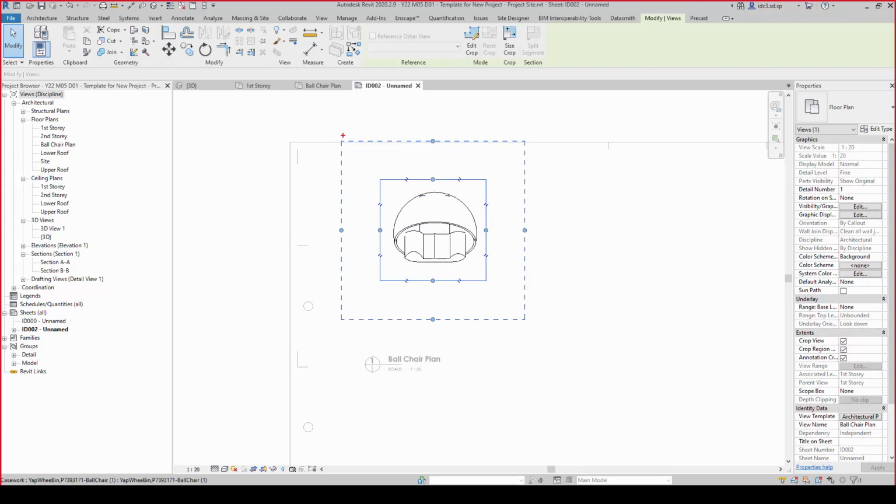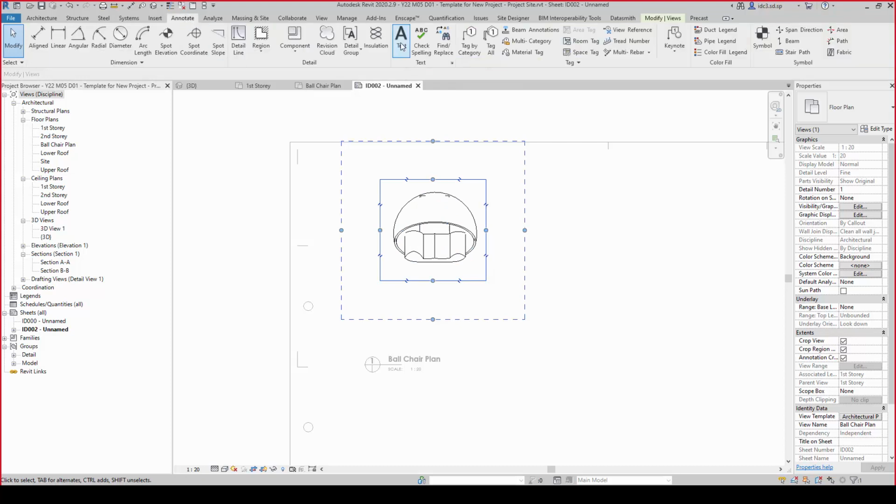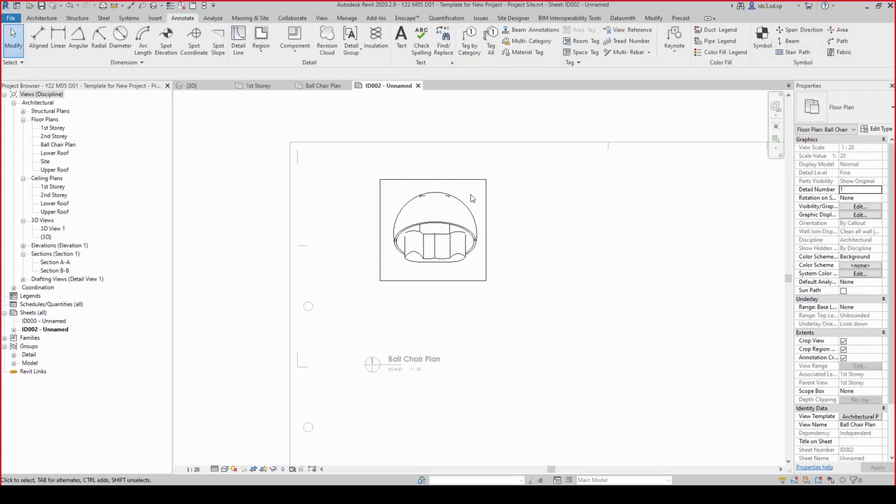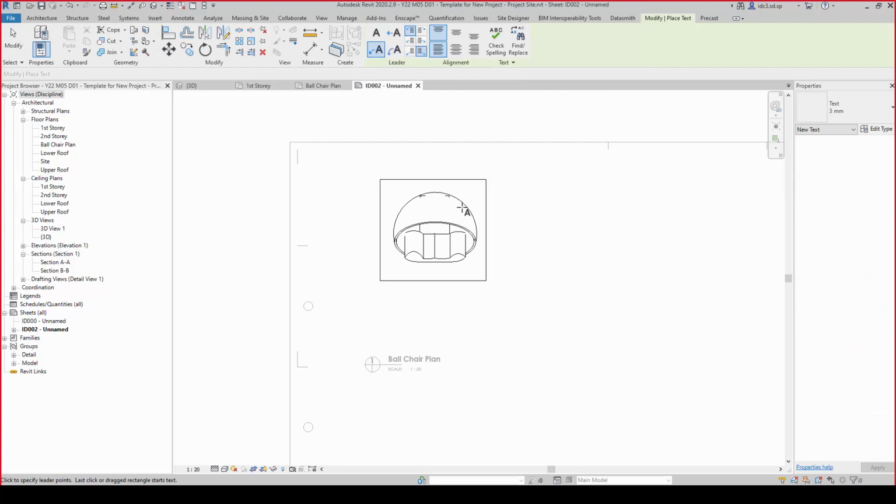Now when we look at this hidden line rectangle here, this one will refer to the annotation objects that are going to be associated to this view. For example, I do a very quick one. I go to annotate, I look for text, and then I put in something here. I've got to be in the view. So annotate text, and then I begin to type something here.